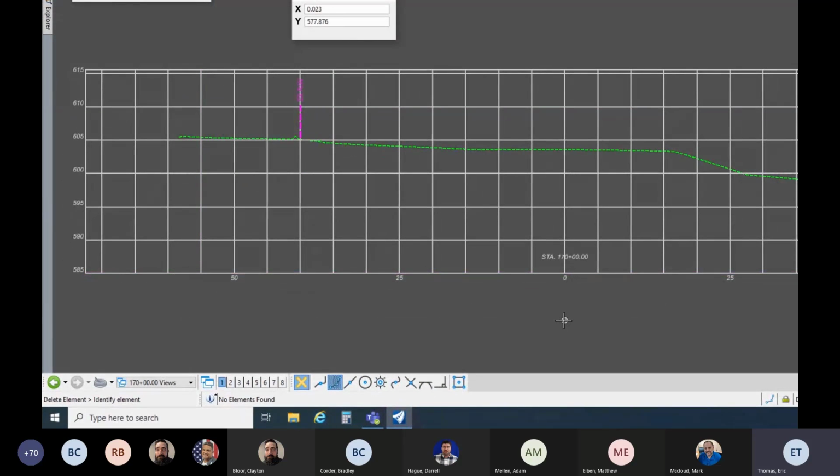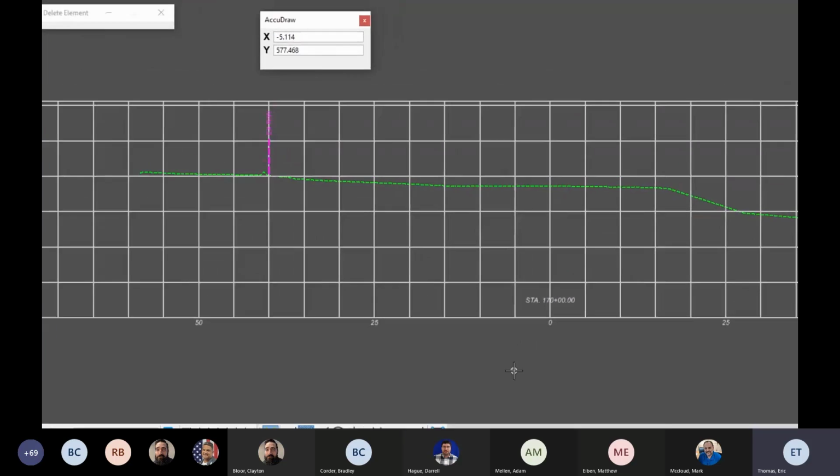It's drawn at its actual coordinates. So this zero offset point is drawn at my x value of 0, and then my elevation here, 585, is the actual elevation. So I can verify that by just issuing a tentative point to snap to the beginning of this line. So it's 2 buttons at once on the line, and it went to the nearest key point since key point snap is active. And I can see the coordinates for that point are 0 and 585, which corresponds to my grid location. So that means I can enter things at X and Y coordinates using AccuDraw.